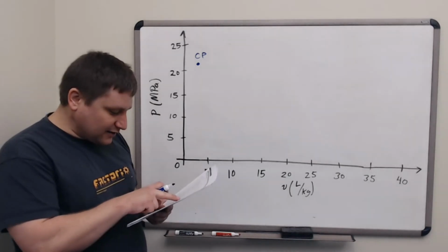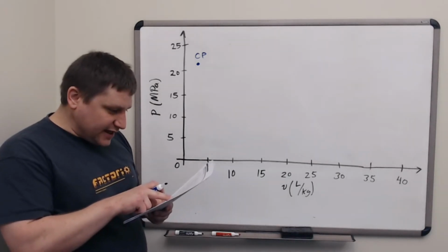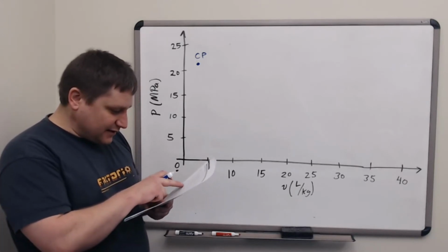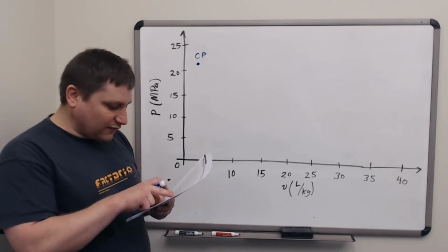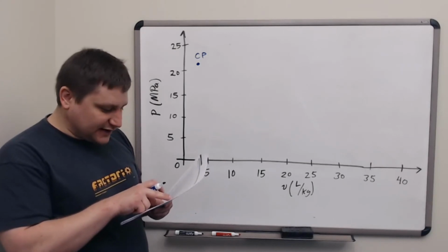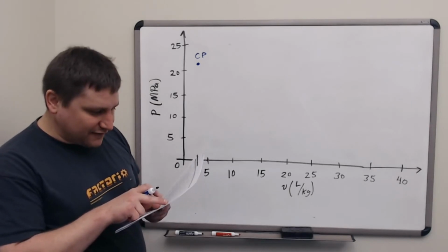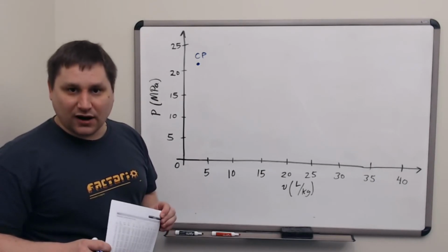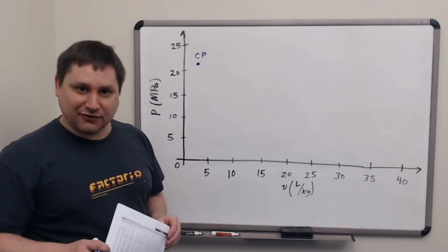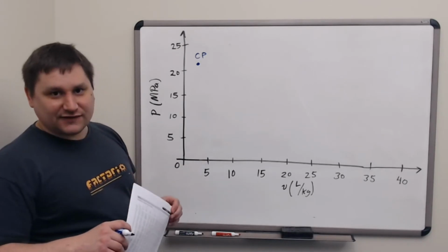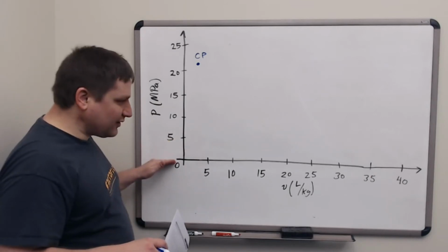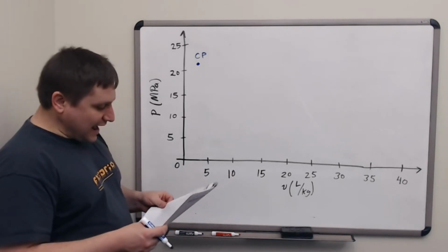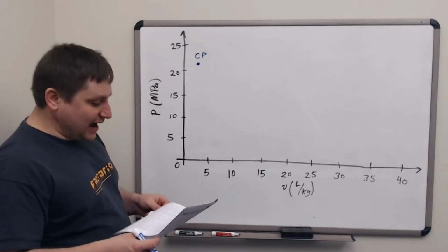The other value we can look for here that we might recognize is the column for the enthalpy of evaporation, h sub fg. If you go to that column in the row for 101.325 pressure, you see that it's 2,256.5 kilojoules per kilogram. This is actually the latent heat of vaporization for water. It's the difference in enthalpy at constant pressure. If we try to draw this row on our graph, it would be way too low in pressure and way too large in volume to fit. So to fill out our graph, let's look at some of the other pressures that are a bit higher.